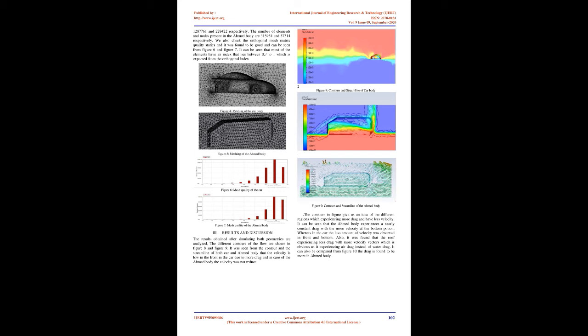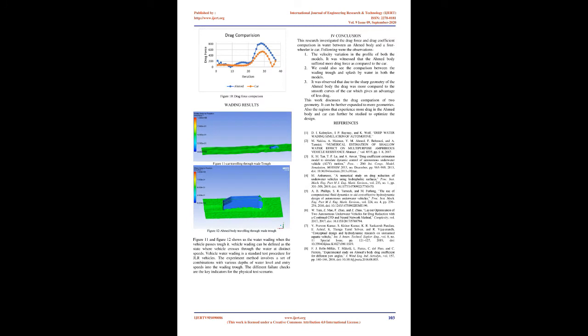The rear slant angle has a robust effect on the aerodynamic drag and lift at the back. Both the drag and lift coefficients change abruptly at the angle equal to 30 degrees. Therefore, this angle is called the critical slant angle. Figure 2, Ahmed body. Figure 3, car body.